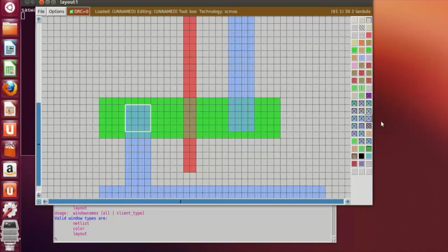Since this is the N diffusion layer and similarly this metal is connected, if you don't connect a contact, then this will just remain overlap, but this will not be connected. So just for your connection, we need these contacts. Middle click. In order to select, we use the middle click button. Middle click in the mouse. Now this is the ND contact.